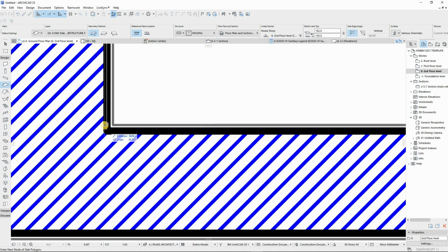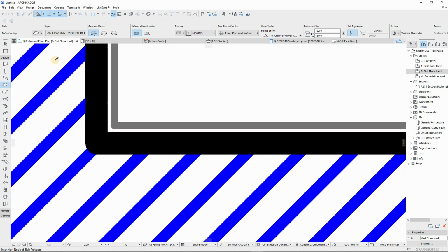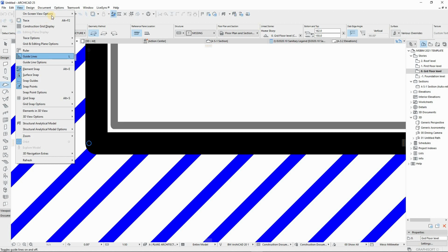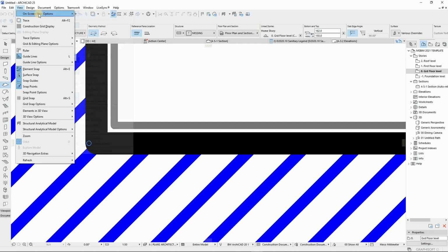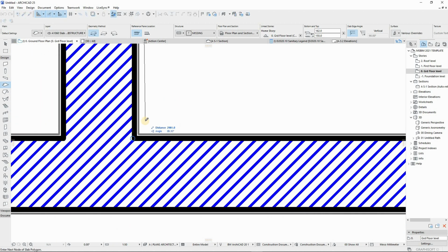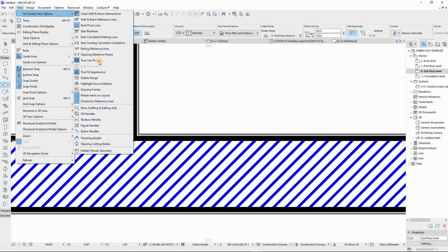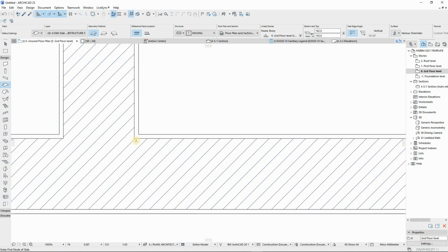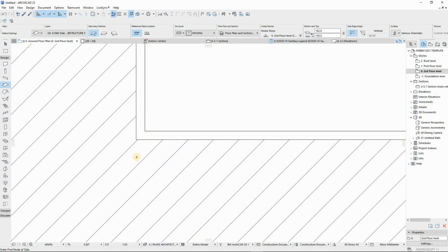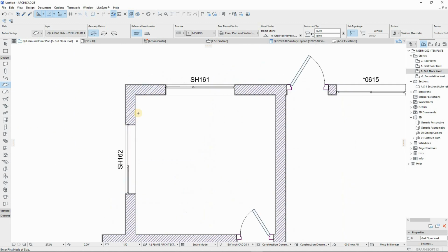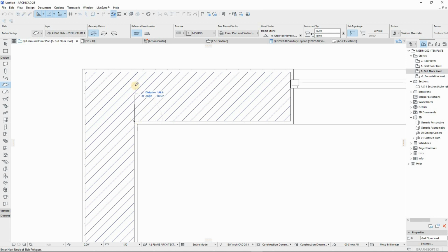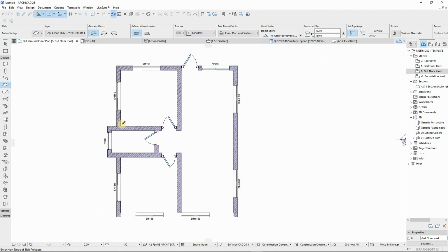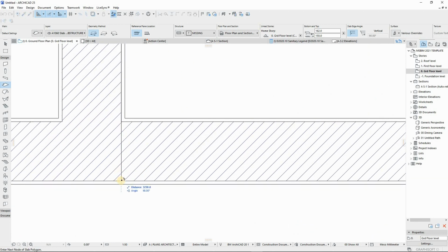floor slab. I'm picking the reference of the brick, the core brick, not the plaster, as you can see here. Let me just uncheck the, let me just do this. Go to on screen, escape, go to the, and then switch off the true line ones. So we have the core brick and a plaster here. So I want my slab to sit right on the edge of my core brick, the plaster is not a structural material. So that's what I will need to make sure I do the right thing.